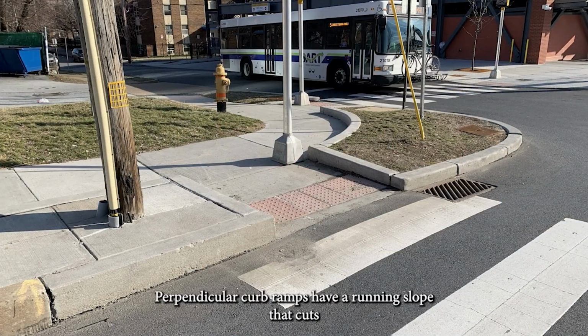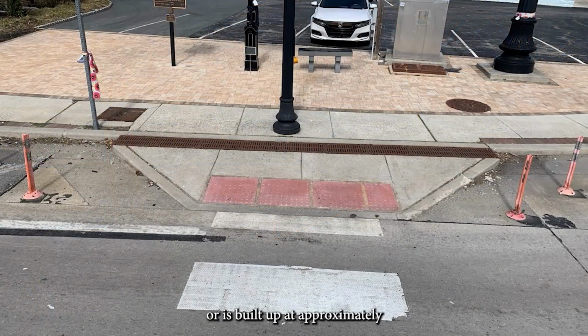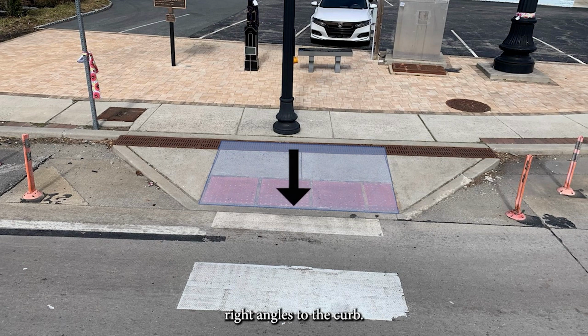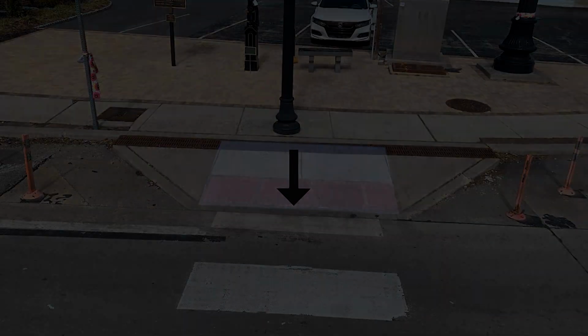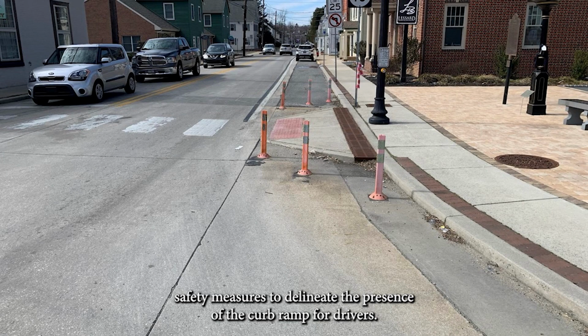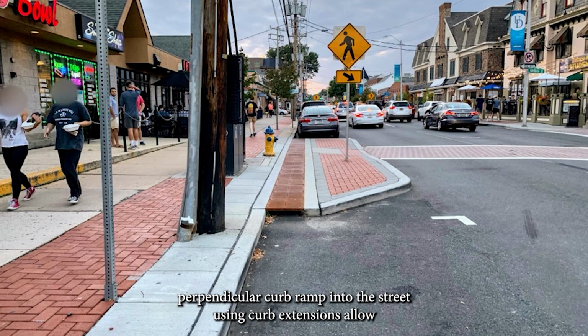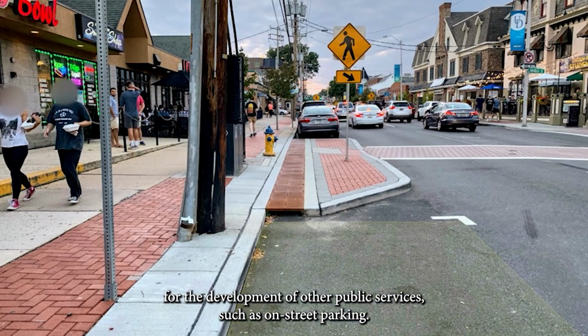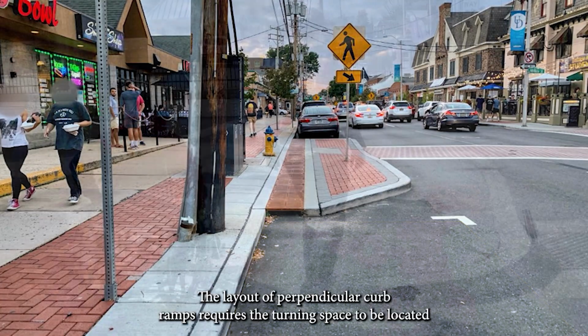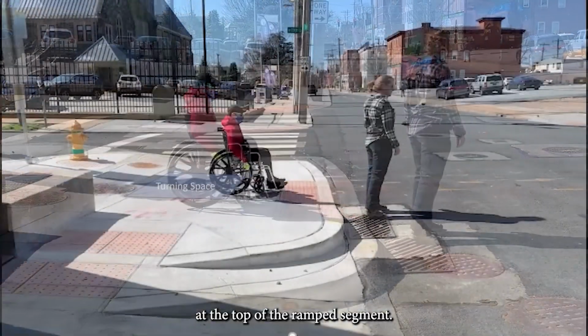Perpendicular curb ramps have a running slope that cuts through the curb line or is built up at approximately right angles to the curb. This approach places the curb in the street and may require safety measures to delineate the presence of the curb ramp for drivers. Building a perpendicular curb ramp into the street using curb extensions allows for the development of other public services such as on-street parking. The layout of perpendicular curb ramps requires the turning space to be located at the top of the ramped segment.